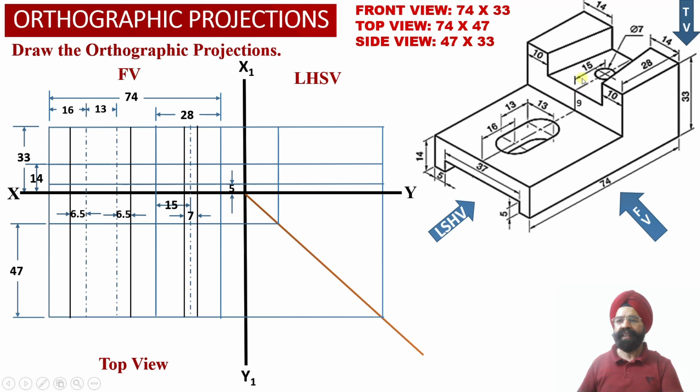Next, we have this surface corresponding to this angular slot which is lying in element number 2, which is a cubical block over here. So at a height of 9 millimeter, the top surface of this slot will be lying over here. So again, another 9 millimeter distance from the top of this horizontal web, which is existing at a height of 14 millimeter from the ground. So we have to mark it out over here.